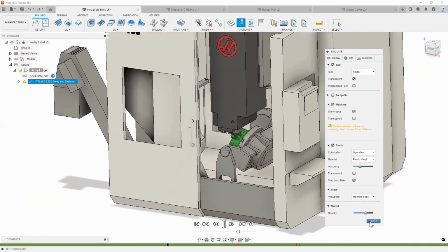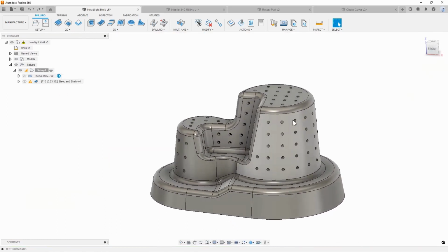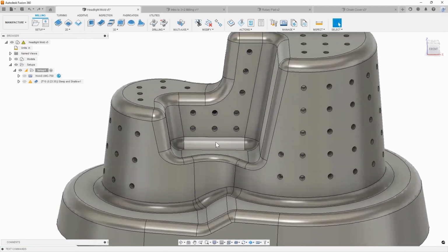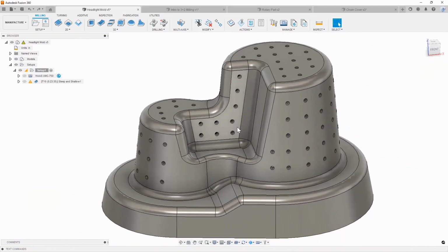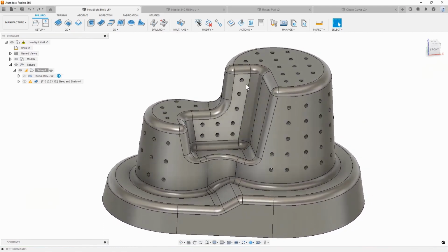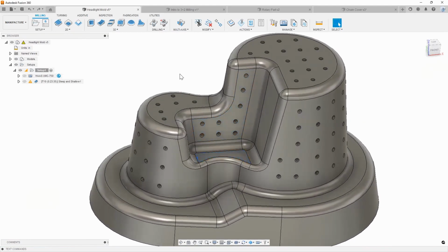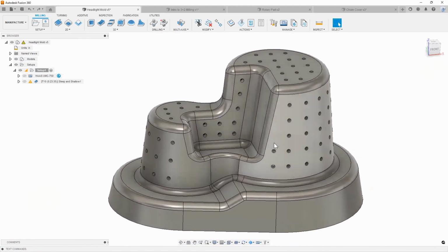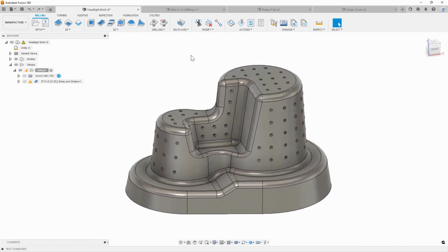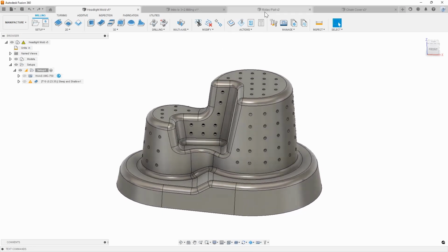So it's a really cool toolpath that gives you, like I was saying, the ability to go from steeps to shallows all at once without having to worry about blending in these areas. Because traditionally, without the steep and shallow, you would have to program separate 3D contour toolpaths and a 3D scallop toolpath or a shallow toolpath, and worry about how you would blend that all together. Okay. So that being said, let's take a look at a swarfing toolpath now.